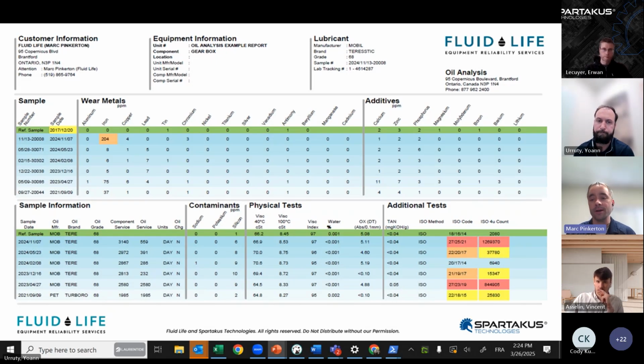So are my results going up or down? Are they staying stable? Do I have any recommendations from my lube suppliers, or even my gearbox OEMs? Did they give me cleanliness standards that are a hard stop, yes or no? Also, asset criticality, right? Is this gearbox an auxiliary one with low oil reservoirs, or is this absolutely paramount to the operation of my mill or whatever, right? So all those decisions are going to impact what you do with the results and if any corrective actions are actually required.